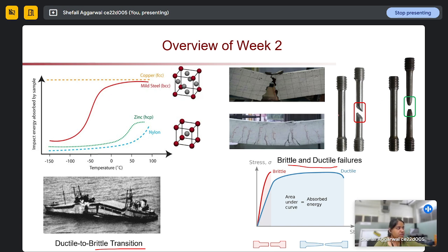If you see in this diagram, this is for metals, ductile and brittle behavior. If any metal rod is stretched, a tensile force is applied to it. Normally, what will happen? A necking will form, and then there will be deformation, right? However, if there is a sudden deformation, if it suddenly breaks, then it will show this kind of shape. So this is brittle behavior and this is ductile behavior. Normally, does our mild steel have ductile or brittle behavior? Any idea?